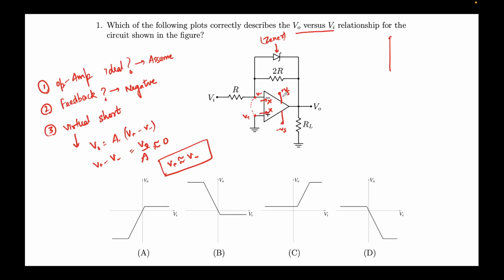And in this problem we also have a Zener diode. All right, so how does a Zener diode perform? Let me first draw this: this is I_D, the current through the diode, and this is, let's say, the voltage on the x-axis, V_D. Let's try to see the positive direction first. The Zener diode behaves like a typical diode. So this means the characteristic will look something like this, and this is what we also know as the V_knee.